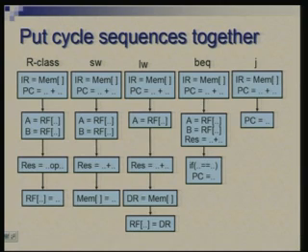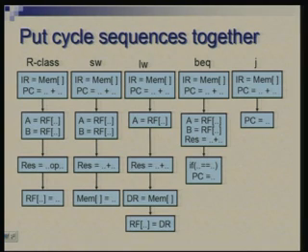So, we have different instructions taking different cycles. You would notice some commonality, something is common, and that's where we can merge. But in the flow of control, at some point we would need to branch, because different instructions require different actions. So, the first cycle is apparently common to all of them, right. So, we could always start with that action and a common state for all the instructions, and once things start differing, we branch to different states.